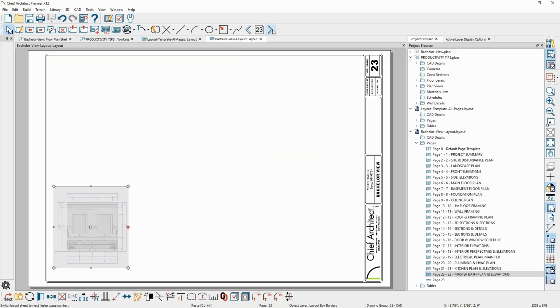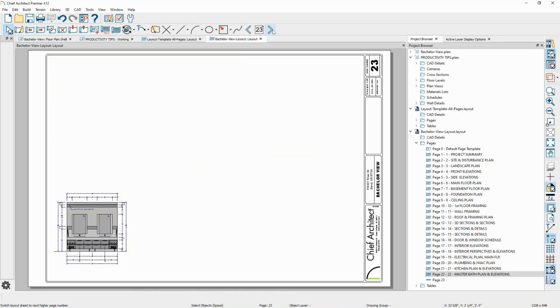Let's assume that I take this wall elevation and I want to copy it. So you can press the copy key, which is in the lower edit menu, or Control C, Command C. Go to the next page. In this case, it's probably blank. Edit, paste, hold position, or Control Alt V, and it will paste it on that page.